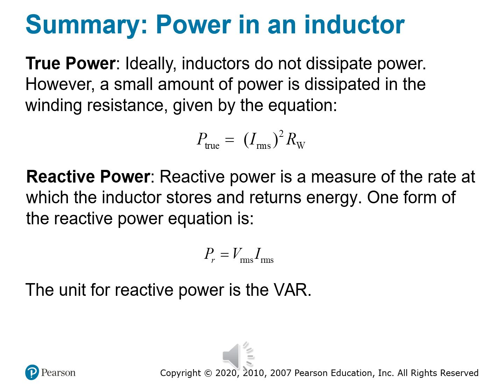Why does that matter, right? Because power systems, motors, and AC circuit designs account for true power, which is in watts for energy consumption, and then reactive power, VARs, for energy movement. And apparent power, which is denoted as VA, is a combination of both. Inductors will increase reactive power demand, and that can affect anything from power factor correction to transformer sizing.